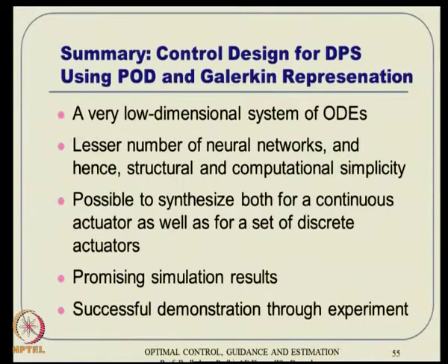And then, as I told before, the people have proposed a different way of doing things, something like adaptive POD and dynamic reoptimization of PODs and things like that. That means you do not generate the basis functions once and then keep on working on that. You can have a procedure where the basis functions themselves get refined as you go along, because you will have better and better snapshot solutions as you go along. So, those kind of ideas are available in the literature. You are most welcome and encouraged to read all of that and then build further. It is a fascinating area of research in my view, and there is a lot of practical significance in general as well.